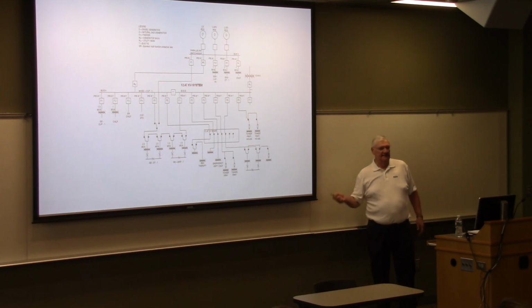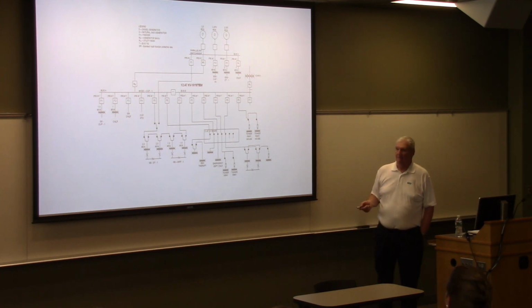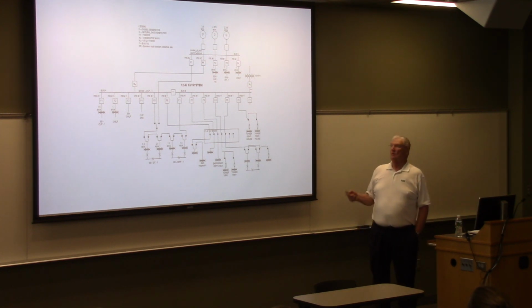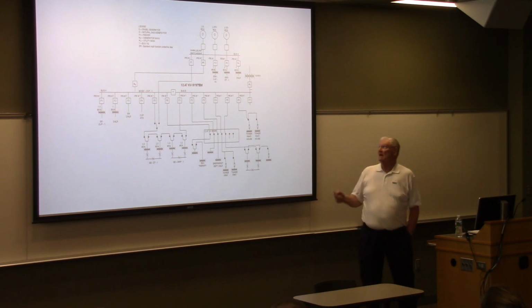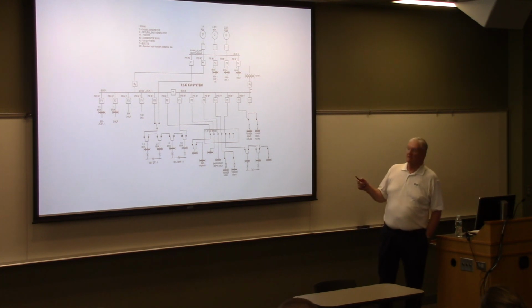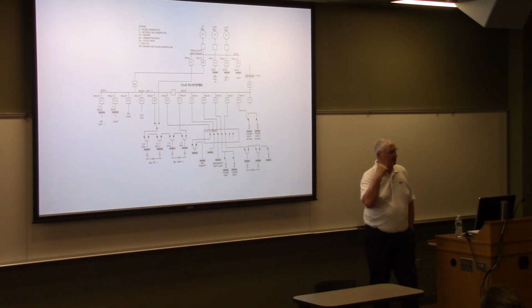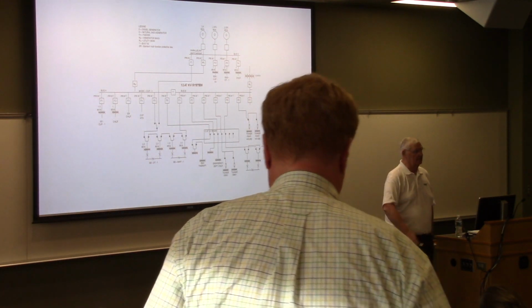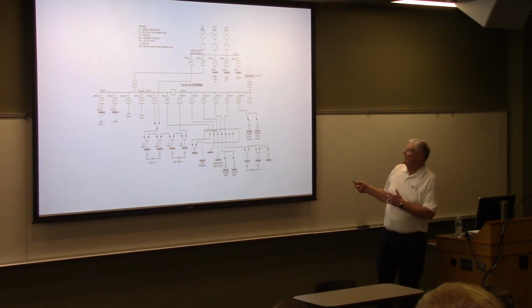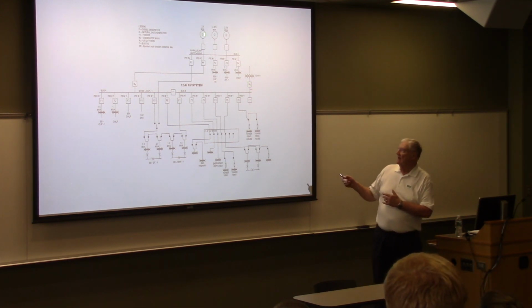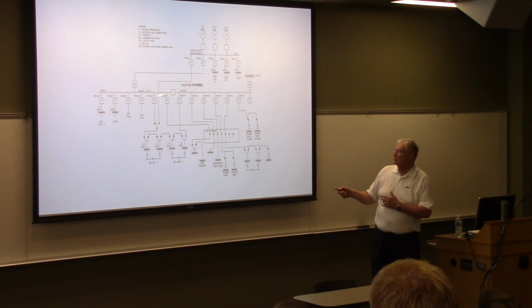Yeah. This is a combined heat and power system. There are two 1.9 megawatt generators up here that are gas fired, and a 2 megawatt diesel, which is an emergency generator. These are CHP generators, combined heat and power. They recover heat to produce hot water for the hospital. Now, all of the protective relaying settings in here in this primary feed is a service to the hospital, and then this is the feed that serves the rest of the switchgear from the generator,